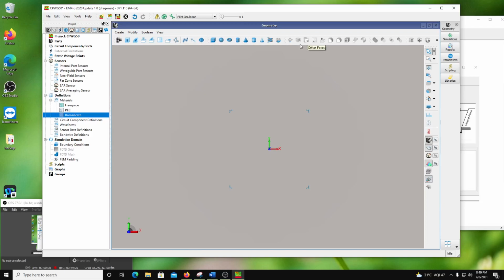Once you are drawing, you can modify the geometry by using some of these functions, which we will see later on. Over here you can combine two bodies: union, subtract, intersect. And this is your chop. Basically it is intersect plus subtract, so subtract plus intersection is chop. You are going to use this chop a lot.